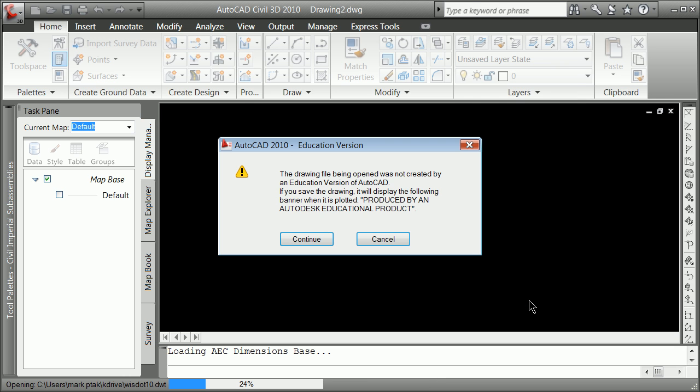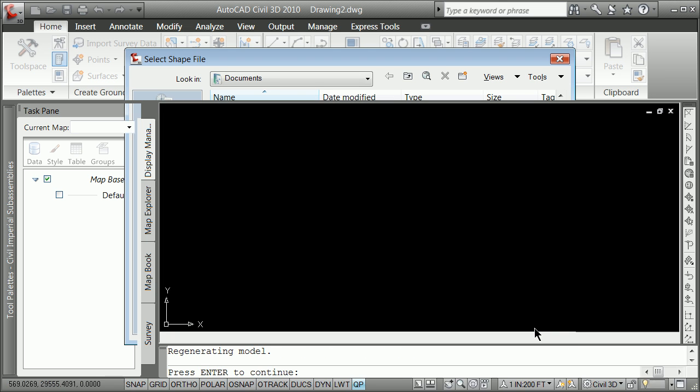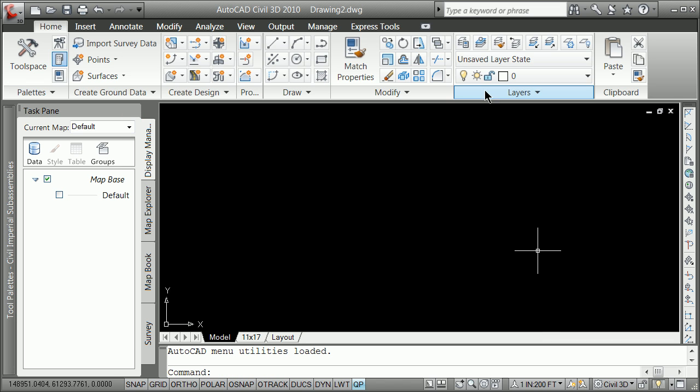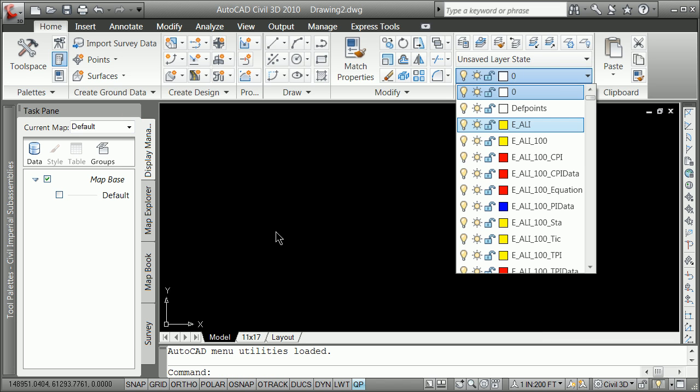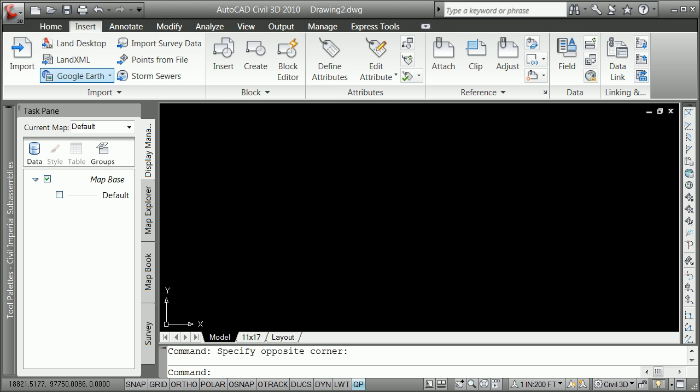So very often these templates are going to come in either a drawing format or a template format. You make sure that you've begun with the right template. You can then bring in the cadastral or the topo, either one. Insert is an AutoCAD command. It is not just this thing there.